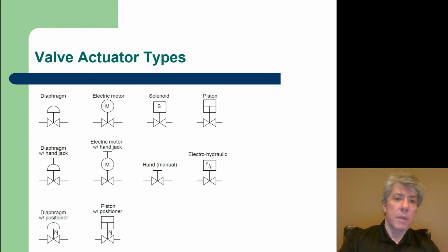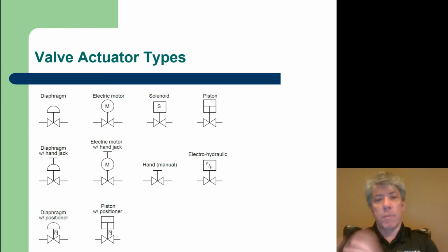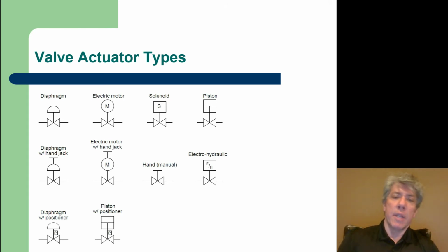Now, going back to valves, really the last slide talked more about the valve body, but if we get into the thing that moves the valve, the actuator itself, then a diaphragm valve, as I said before, is a very common one, the one on the upper left. On the other hand, you don't have to have air move the valve stem in order to control the valve. You can have an electric motor control the valve stem, and that's what's shown next.